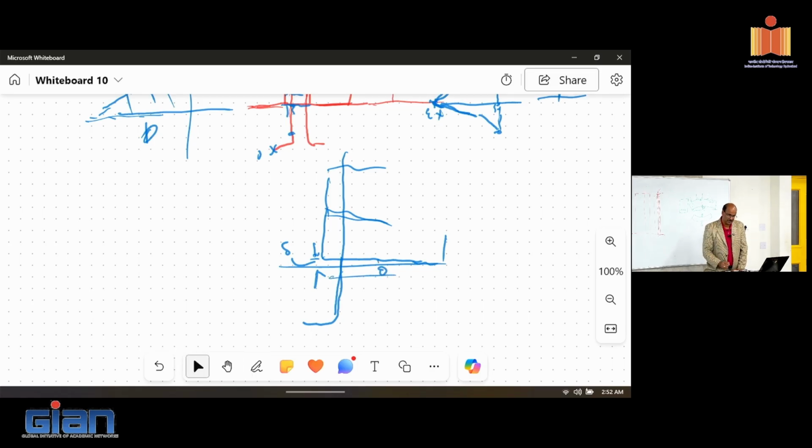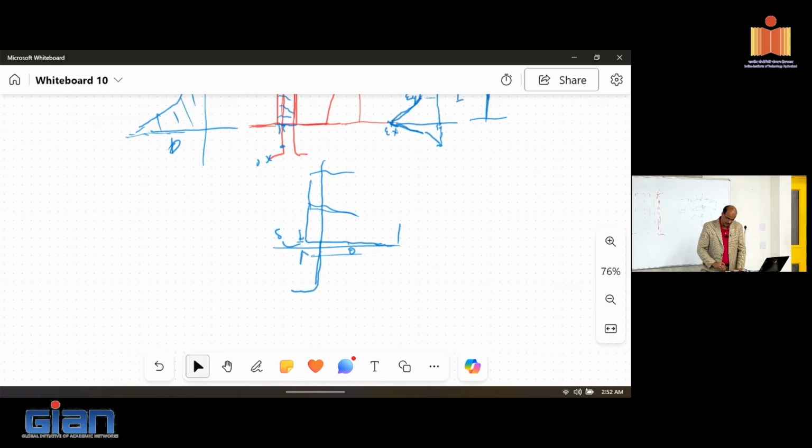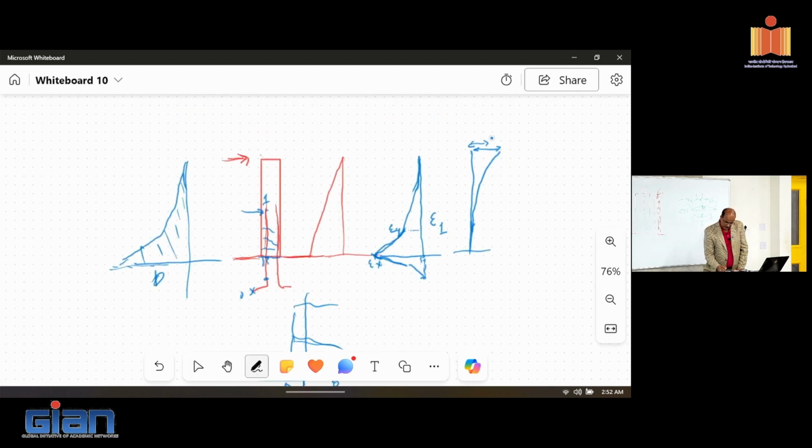So the theta is pretty small, but if you have a 3-4 meter column, what you will find is that this additional displacement basically comes from those penetration effects. That component could be as much as 30%. It's not small because you have a plastic strain, potentially, if it's an earthquake-like situation or you're trying to develop the full moment capacity, right?